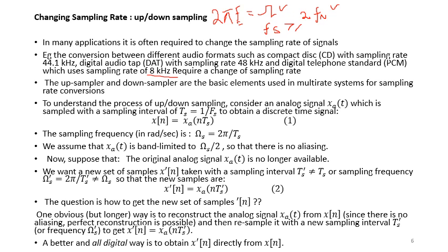Because we have the sampling frequency here of 8 kilohertz, that means 8 kilohertz equals 2 times the maximum frequency, which we represent by Fn. So that means the maximum frequency possible with the standard telephony is 4 kilohertz, which is very low.